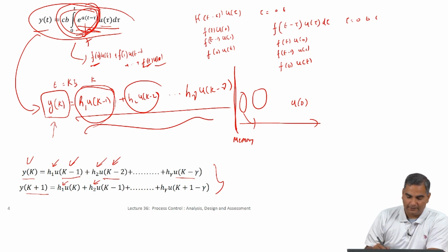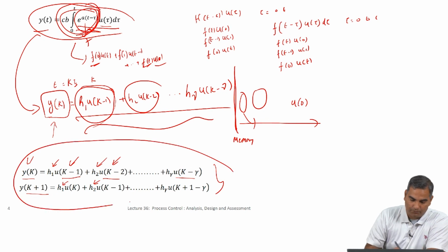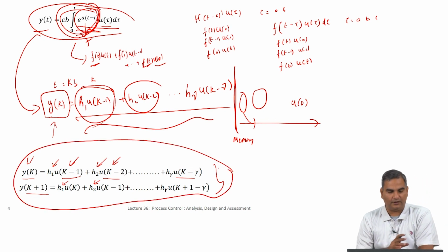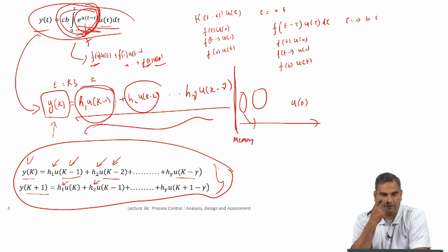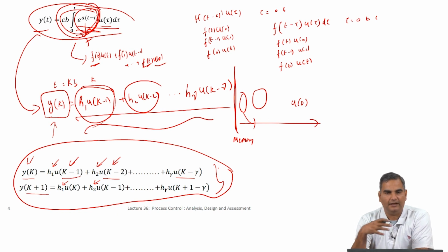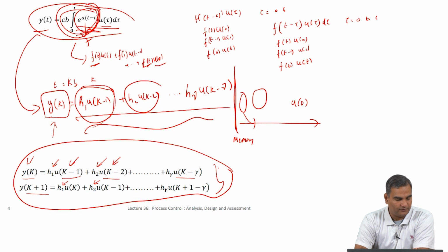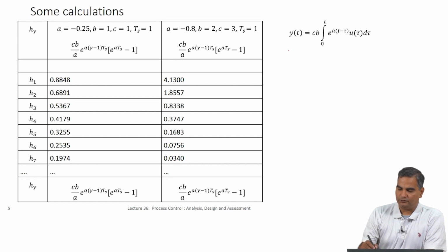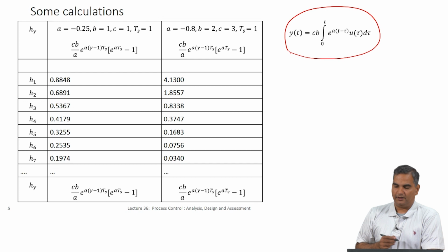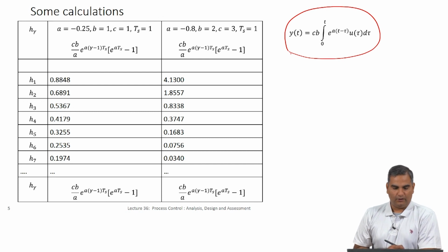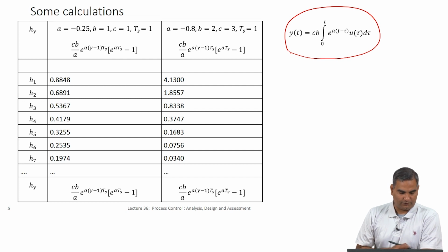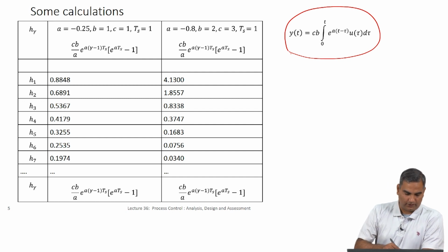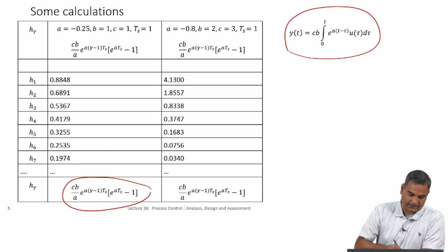Now, you see that you have a model between output and the inputs in the past. So, this is the critical model that we were looking for to complete this idea of model predictive control. So, let us take some examples to show you how this will work. I showed you the expression that we had derived mathematically. Now, when you convert this to the coefficient form h gamma, mathematically you can show that if you use this weighting, you will get an exact result.